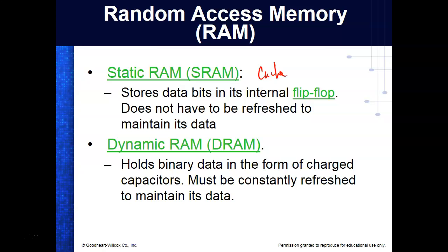But if we didn't refresh dynamic memory, it would lose its content. Originally, we had to do it with programs. Then they came out with a DRAM controller, which basically does it for us. And now it's integrated into the chipset that's running your phone. So this is all the refresh of the dynamic memory is, and it lets us use the cache. The cache allowed us to use DRAM for our main storage.